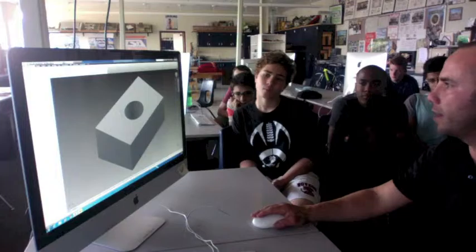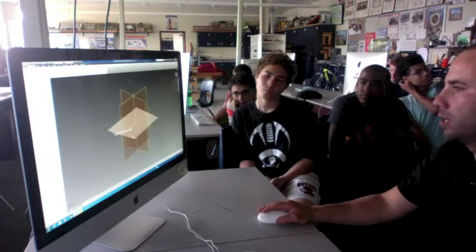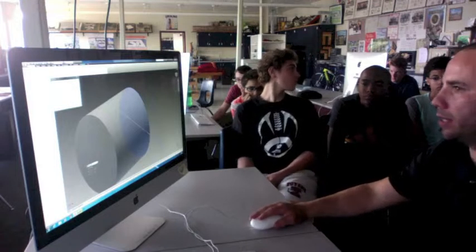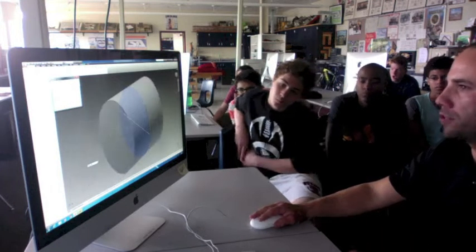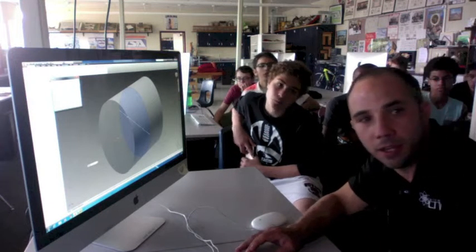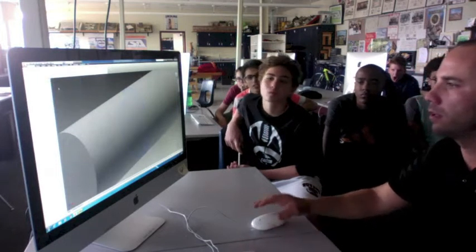Okay, now leave that file up. File, New, Standard Part, Create, Start Sketch. I'm going to pick the XY plane again. I'm going to pick a circle. I'm going to sketch the circle and make it 1. Finish sketch, extrude it, and I'm going to go symmetric again, and I said up there the part is going to be 3 inches long, and there's my part.